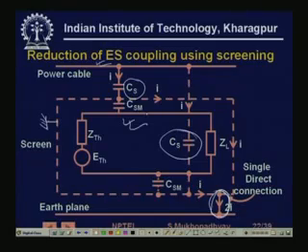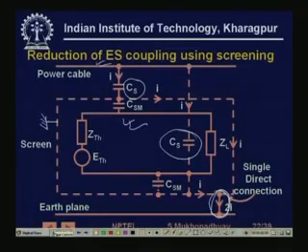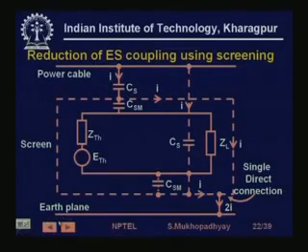Similarly, you can have a similar principle called shielding. Sometimes in electronic circuits, especially at very high impedance, very susceptible points, typically the amplifier inputs, where a small signal, because of the very high gain of the op amps, can produce a large noise component at the output. Such sensitive points, like the op amp inputs, are sometimes surrounded by what is known as a guard ring. These are all to reduce electrostatic coupling with external sources such as power supply voltage or even other sources.